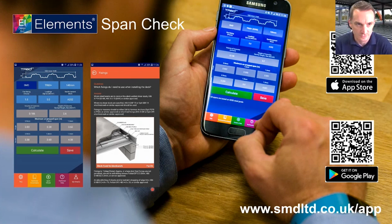And I think the last one, although there may be one more slide, we have the Elements Span Check app. This is very much based on the White Book, but a quick tool for that, where you select your loadings, your fire rating and your mesh, etc., and it will give you your maximum unpropped spans. It was born out of the idea of people on site having a way of checking, if they had to cut a sheet down, or if they were wanting to rotate a span, would that profile work for the required criteria. It's available on Android and Apple.